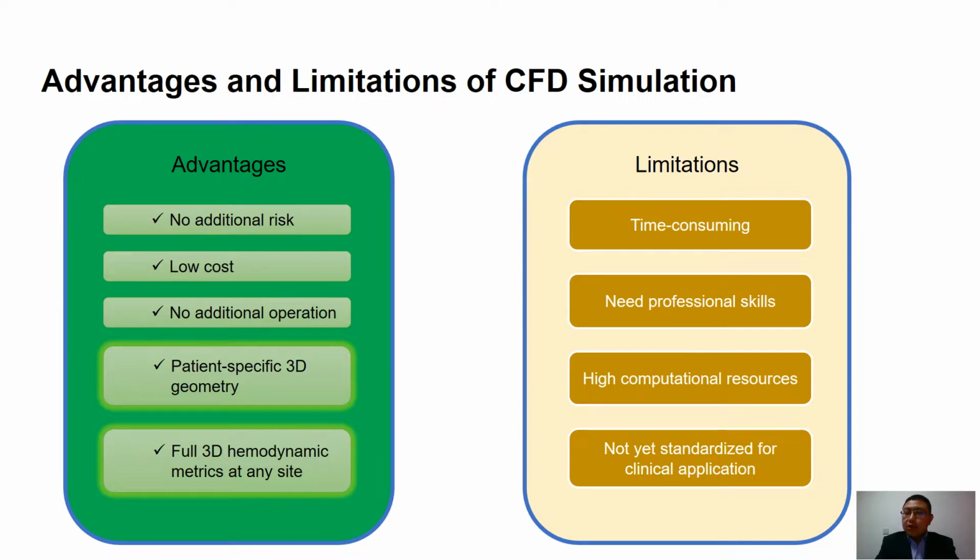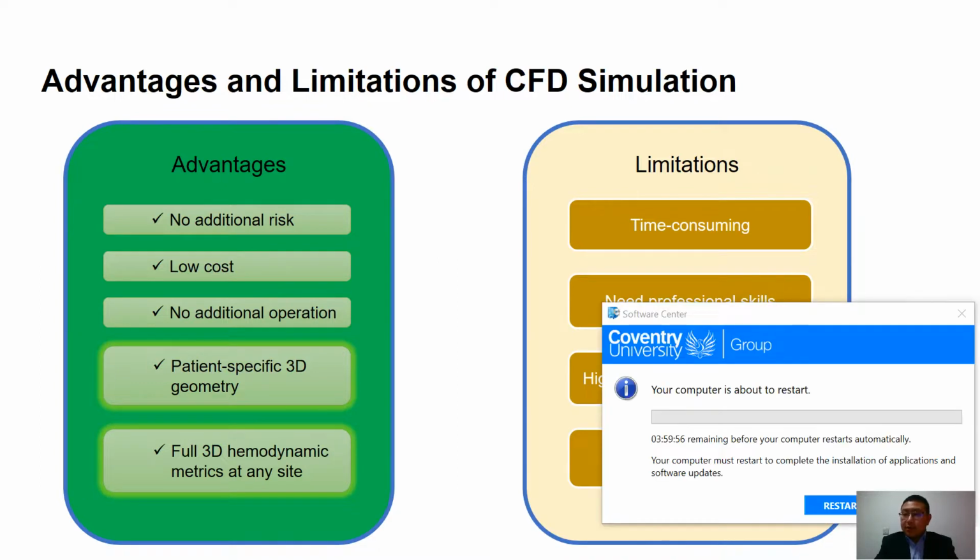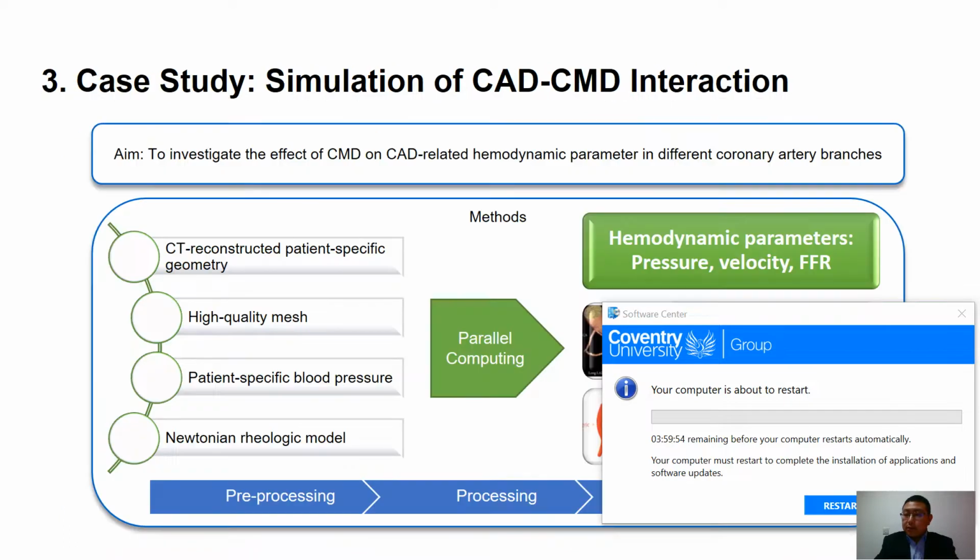Another important limitation is the need for high computational resources. A model can comprise millions of elements in its mesh. If we use a normal computer, sometimes a simulation can take 4 days. Therefore, a high-performance computer is indispensable. Finally, the CFD models and the procedure of simulation are not standardized. There is still a long way to go towards clinical application.